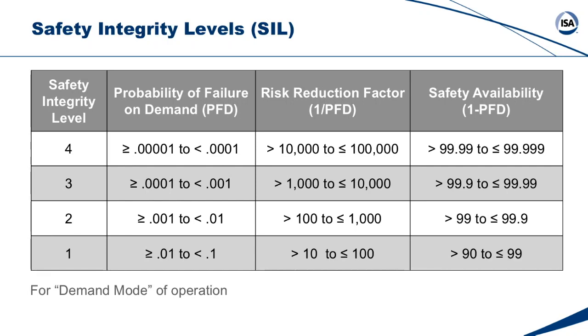Most people don't see a significant difference between 99% and 99.99. To most people, that's less than 1%. Oh, well, it's 2 orders of magnitude different. It's just not easy for most people to see. So there was one guy who's retired now, and he came up with one over the PFD, and industry now refers to that as the risk reduction factor.